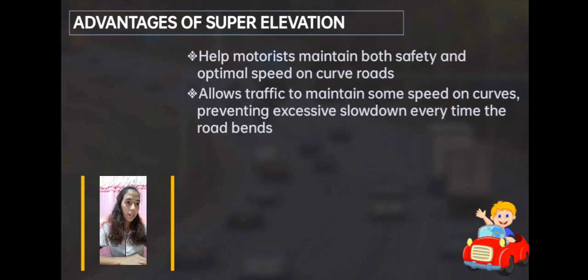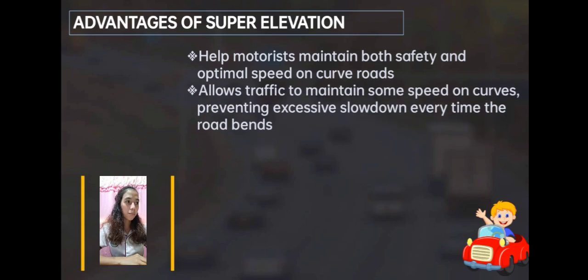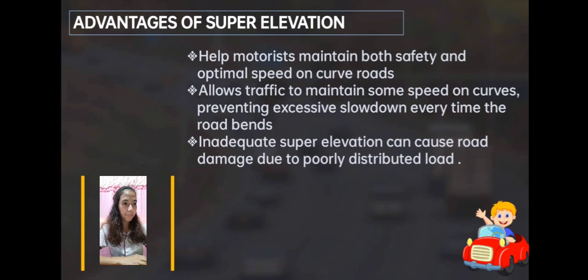Next is, it allows traffic to maintain some speed on curves, preventing excessive slowdown every time the road bends. Next, inadequate super elevation can cause road damage due to poorly distributed loads. So, disadvantage kapag hindi tama yung super elevation, pwedeng magkaroon ng road damage.